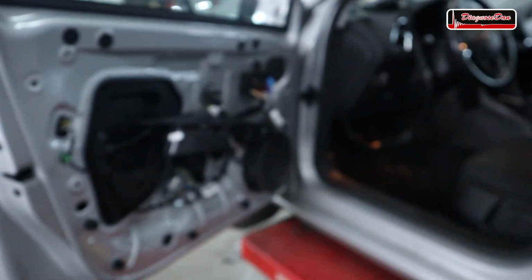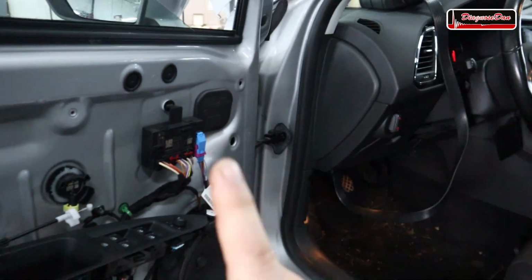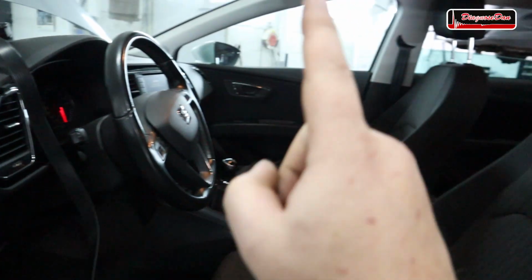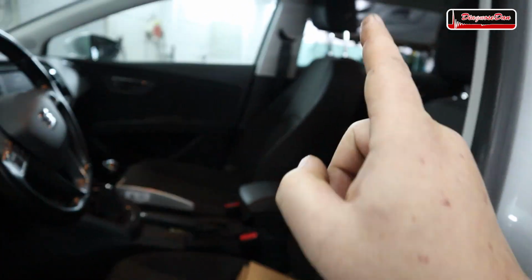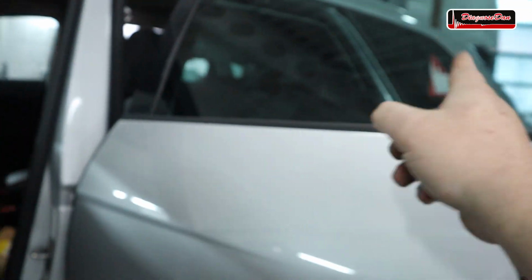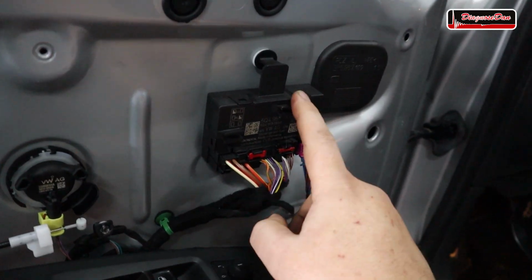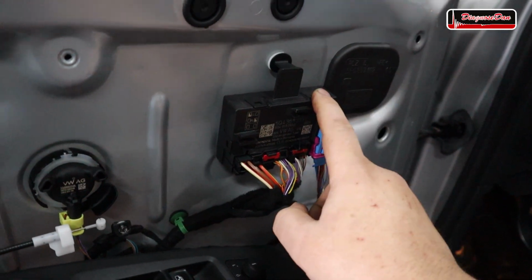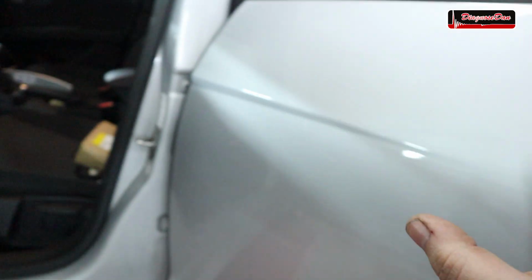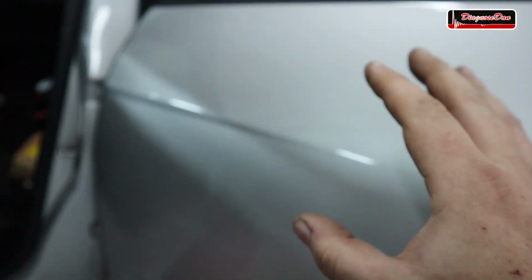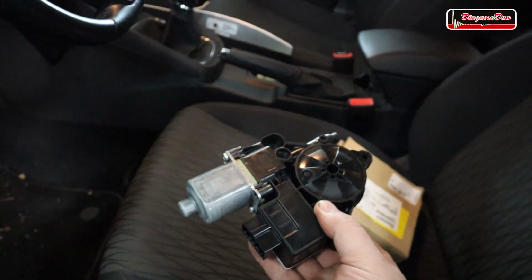What this module tells us is there's something going on with the communication among the modules. We know that module is listening because this window is rolling down. That one is listening. The only one that's not listening is this one right over here. So what this module is trying to tell us is that there's something going on in the communication between this module and the module in the back. Now, this could be a bad module, but that module has already been replaced.